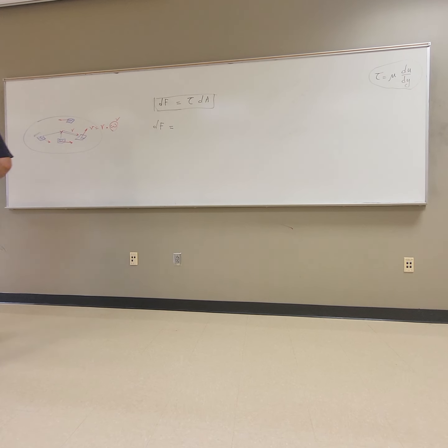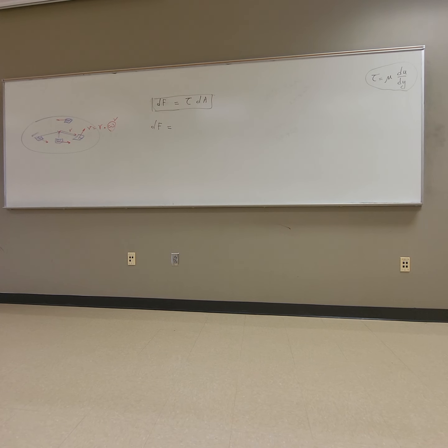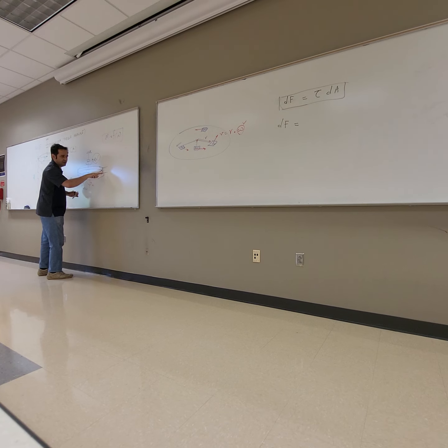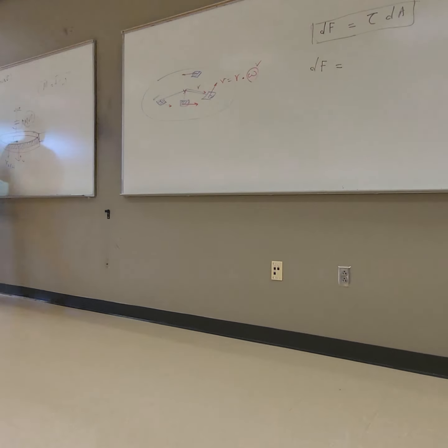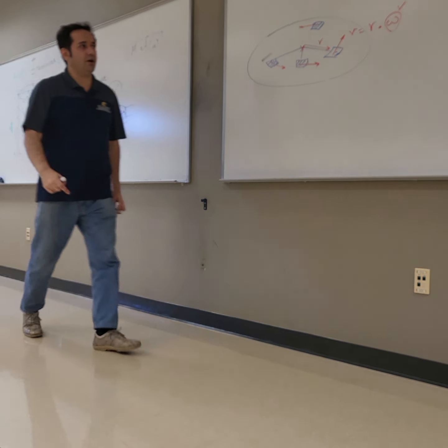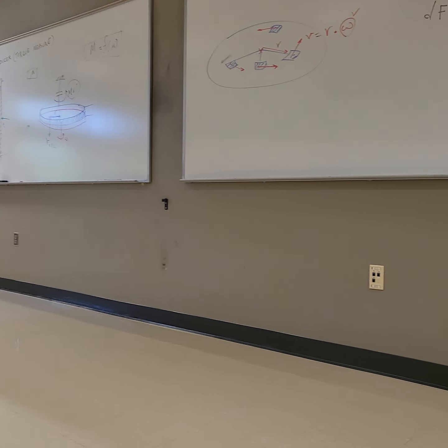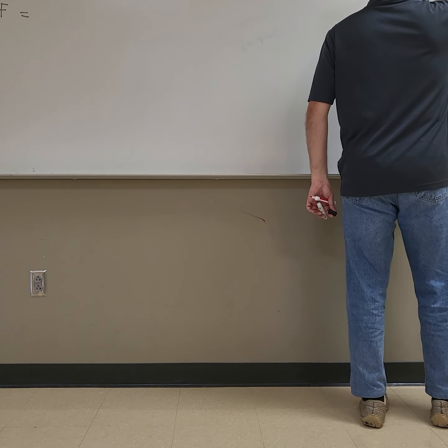So look at the distance gap between that. If you look at the gap here, the velocity at this bottom is V, right? The velocity at top is what? 0. So in fact, for this delta u, the change in the velocity is V minus 0. What's the change in the y?